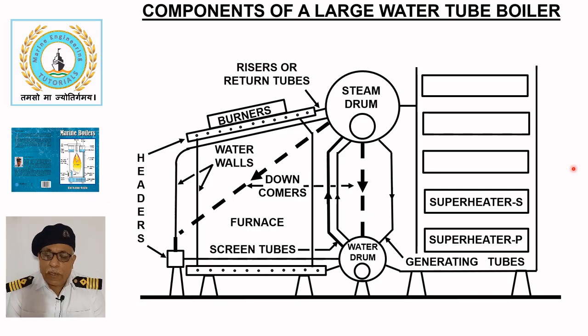They must be protected from direct radiant heat because steam has a much lower specific heat than water, making the tube susceptible to overheating. Superheater support tubes, which are larger in diameter, provide water-cooled structural support.